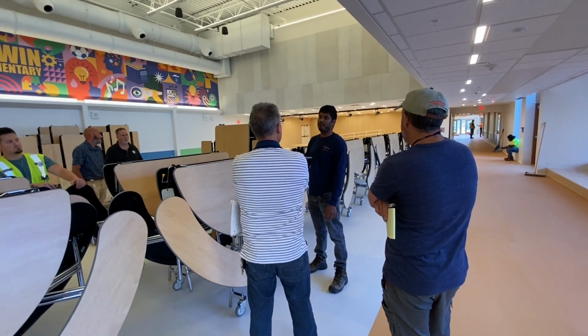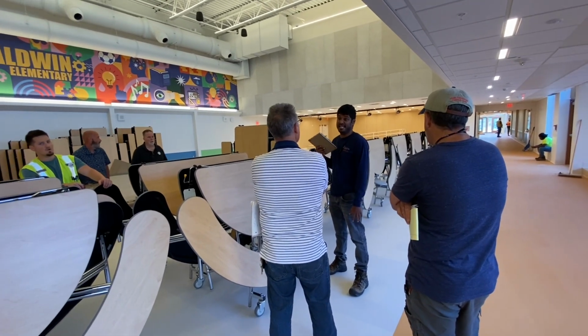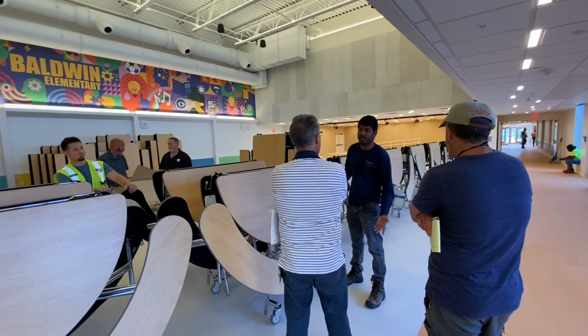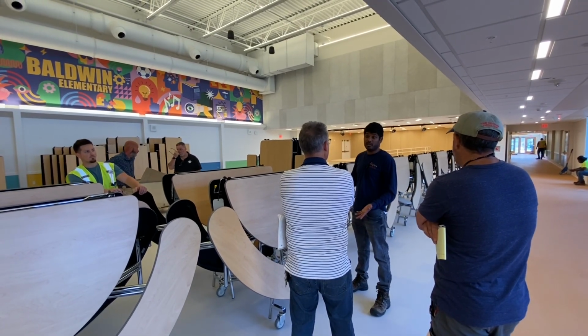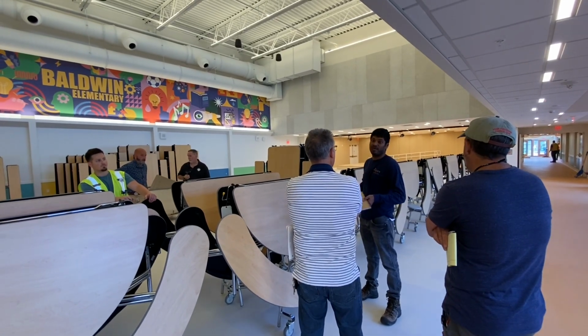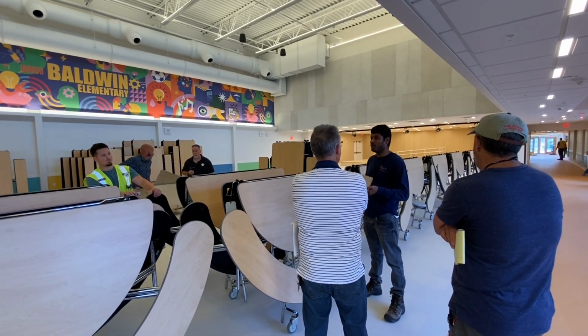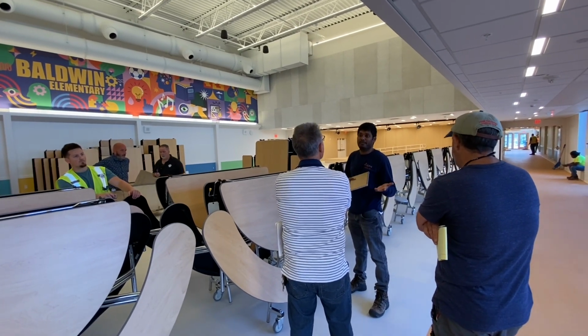I need my own local VLAN so that I don't have to ask 95 IPs from the school. I don't want to put my controllers in the building network. First of all, they would have to create a new VLAN for us, and I don't want to jam the traffic with all my BMS controllers.